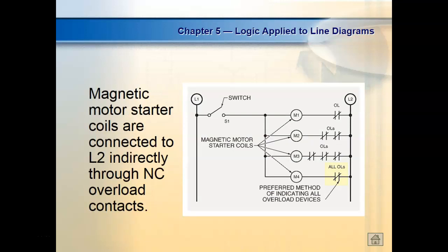Magnetic motor starters that have overloads on them, we will have the overload contacts. This has become more popular now. Used to have an overload on every phase, but what's happened is they designed it so we only have one reset. So when you hit that reset, you're resetting all overloads anyway. So instead of drawing all three of them, standard practice now is to draw only one. But it's also taking up the other two, right? You understand that? Everybody understand that? And these are wired internally too, so you don't really see the overloads wired in series. They're actually wired in series on the overload assembly itself.